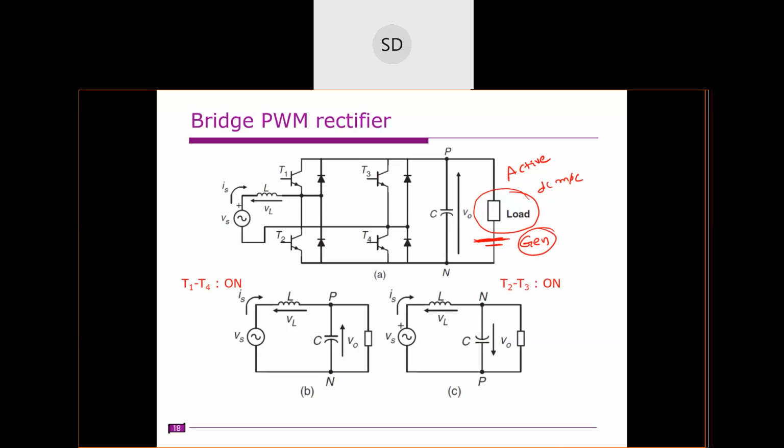Or you need to connect a large battery and make sure that, for example, this is 200 volts, we are maintaining 200 volts across this one. So it must be the generator voltage, which must be greater than this 200 volts. Then only the regenerative can occur, right? If it is around 230 volts or something like this, then only this regenerative can occur. Clear?